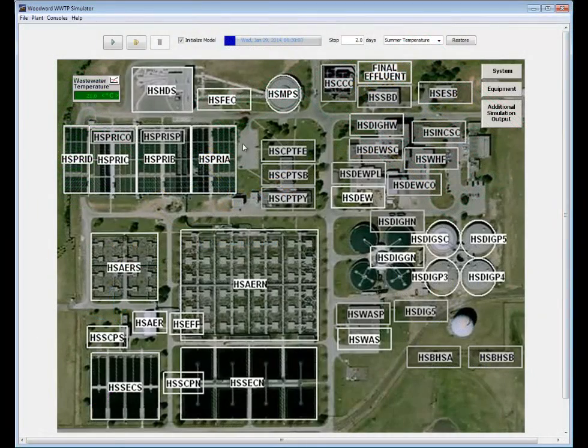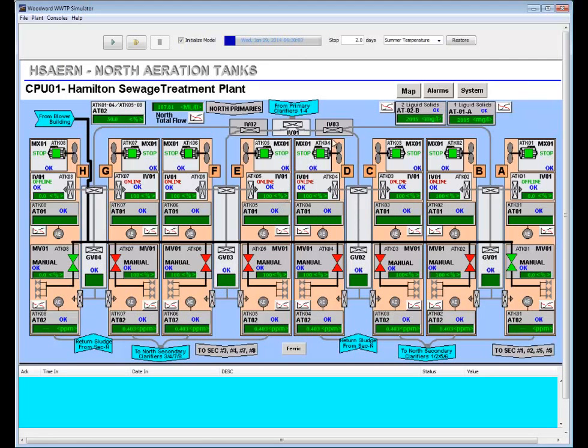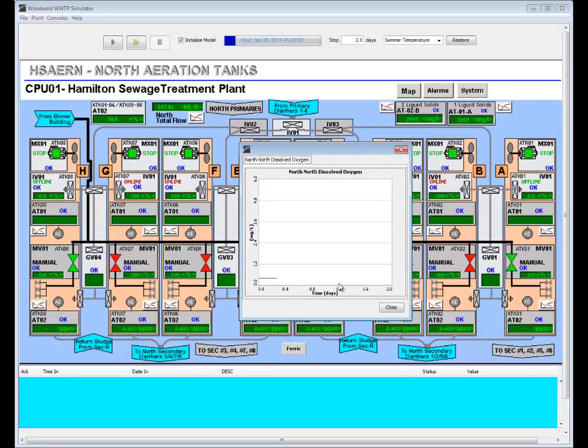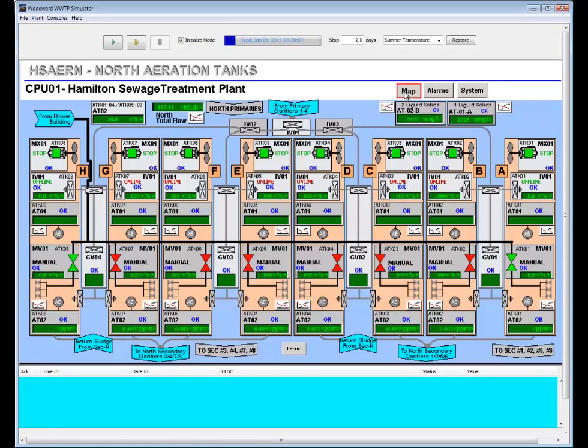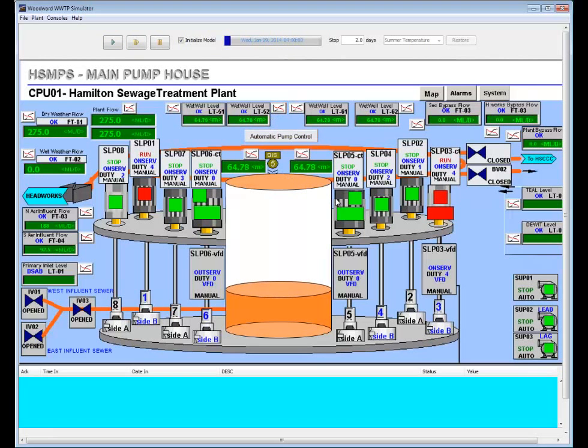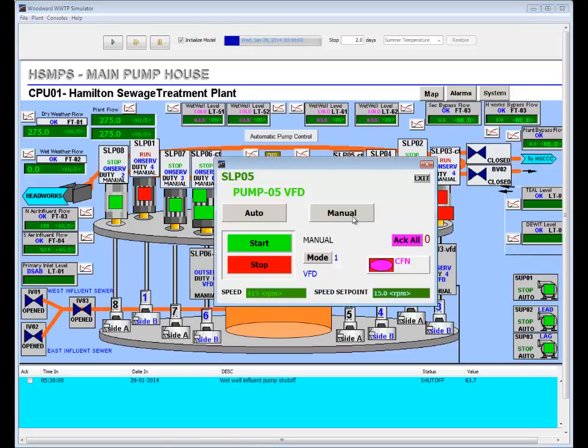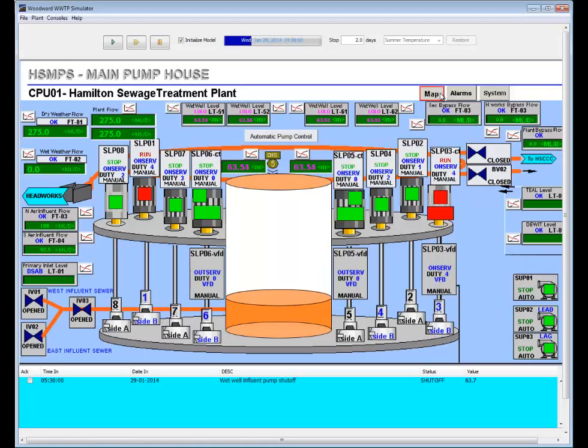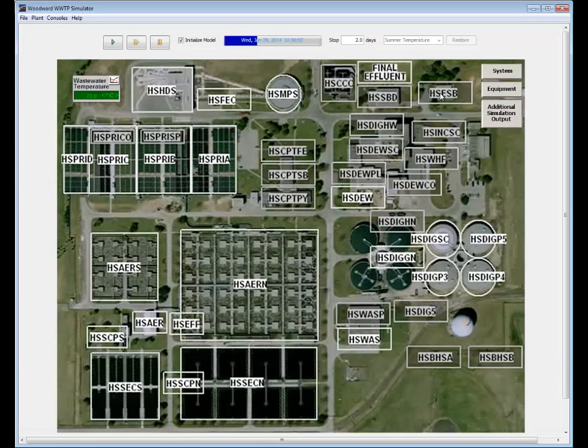And lastly, this interface was designed with the goal of replicating an existing SCADA system. The model is connected to these images here that the operators are already familiar with, and the model outputs are placed into the same windows where the SCADA results would normally be shown. So users can come in and browse around. Ones that are already familiar with the SCADA system will know how to open up menus, turn on and off certain pumps. We replicated a number of the alarms and other signals that come from their system. We are doing that from the model here.